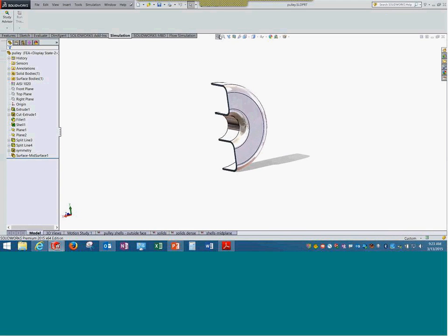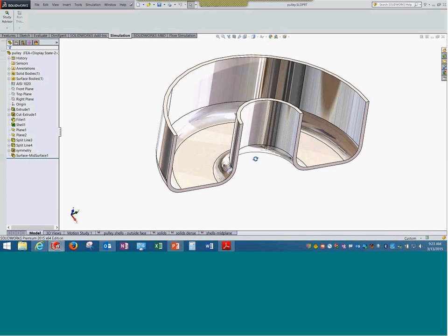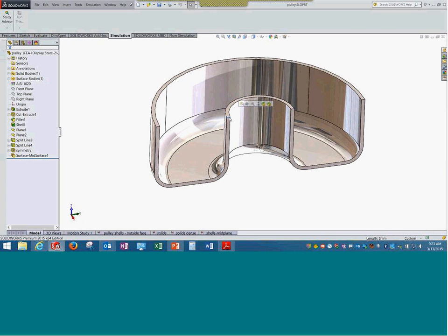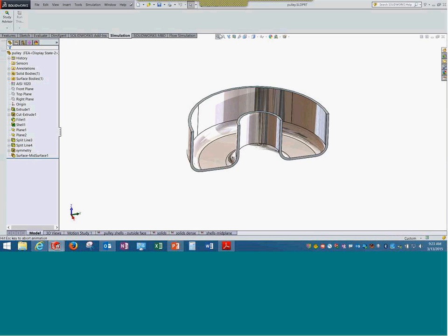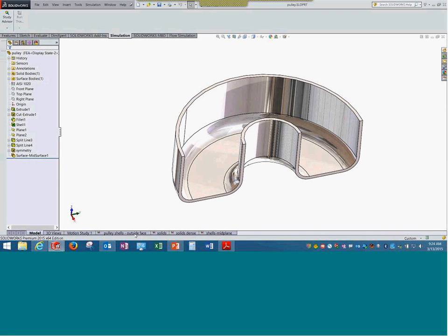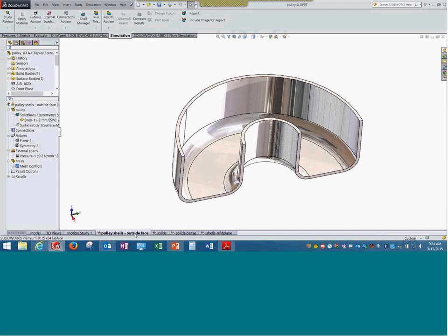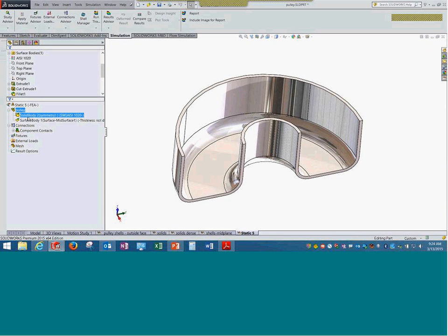I think initially I have already introduced you to shell elements, and if you observe this, this is a classic example wherein the thickness is around 2 millimeters and is consistent throughout the geometry. It is the same, right? So such a model is eligible to be treated as a shell element. Now, when we create these shells, we have different options. Let me try to create a new similar study so that I can quickly show you from scratch.